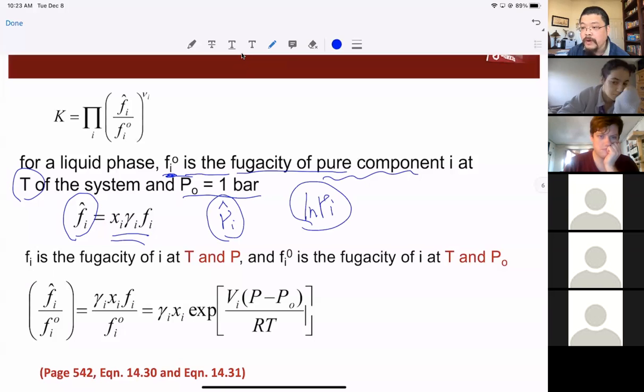And of course, those components will have their corresponding ABC kind of coefficients. So the intermolecular interactions will be included in those coefficients. Okay, we do have to take care of the interactions of non-ideal solution, but not by the hat, but by figuring out those coefficients in the activity coefficient models.